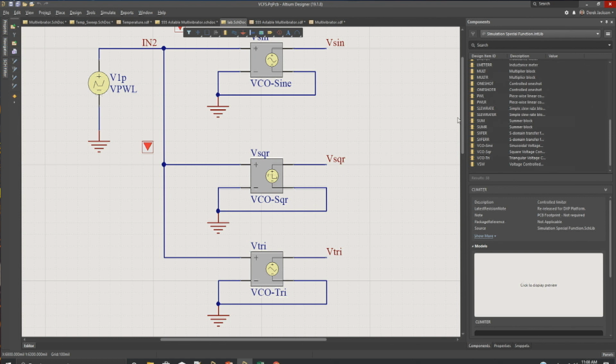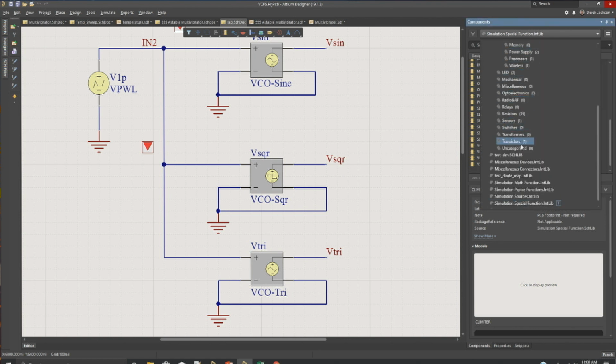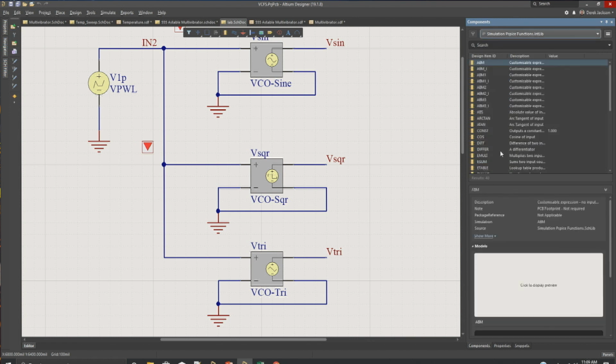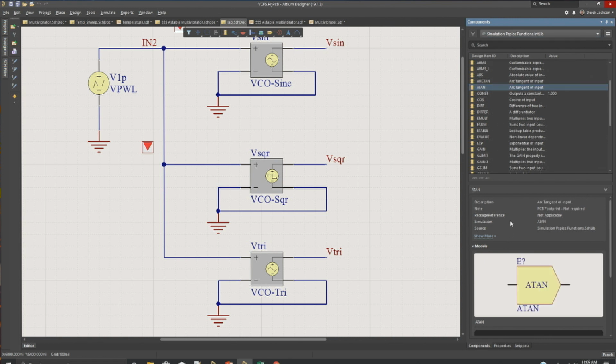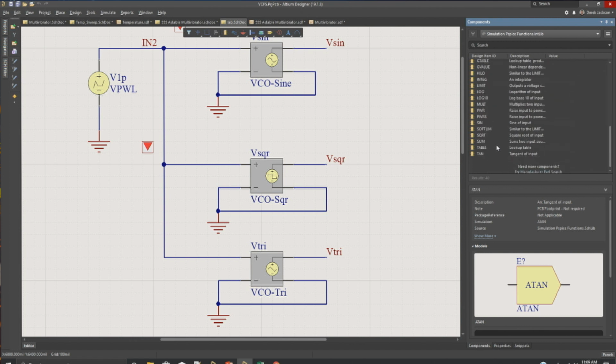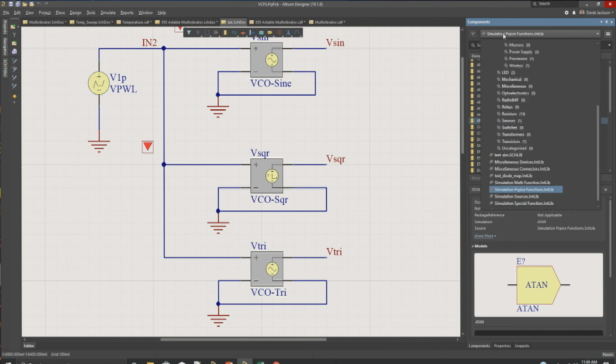So one of them, you can use these special functions. There's also PSpice functions. What they had done is they had modified the controlled voltage source and controlled current sources with an equation, and they call it analog behavioral modeling. So you can get a lot of different waveforms created using those. Now with Spice 3, they came out with the B device, and the B device is an equation that lets you write in pretty complex formats. But we have the PSpice functions here.